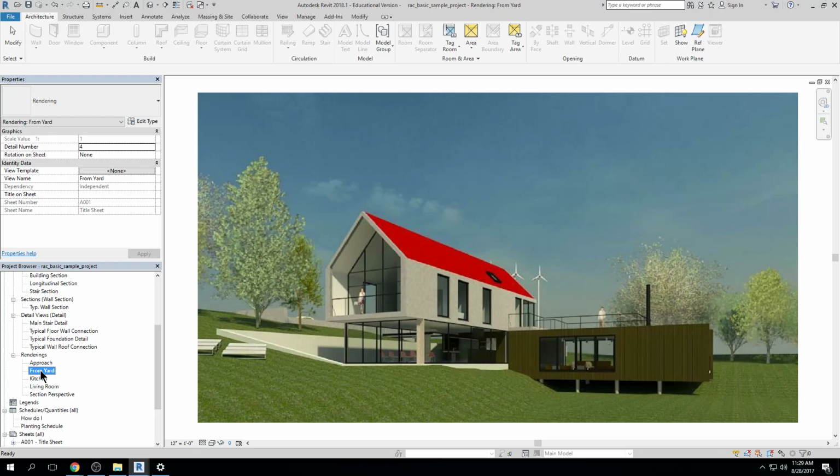You're building these dumb objects that don't represent a floor plan or an elevation or a section. Whereas in Revit, when I build 3D elements, they can be viewed as a plan, section, or elevation. They have integrity, and I can use them for 3D and 2D construction documents, which is really nice.